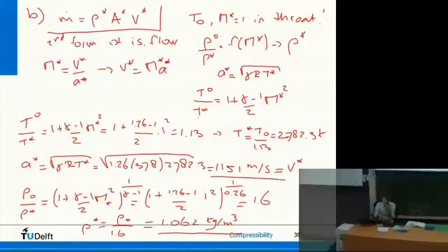Got a few questions in the break that were good questions I would like to share with everybody. One was on this exam question where I skipped a step because I prepared slightly differently. Of course, here we have computed the ratio of the total density over the density in the throat, but you don't have the total density yet.